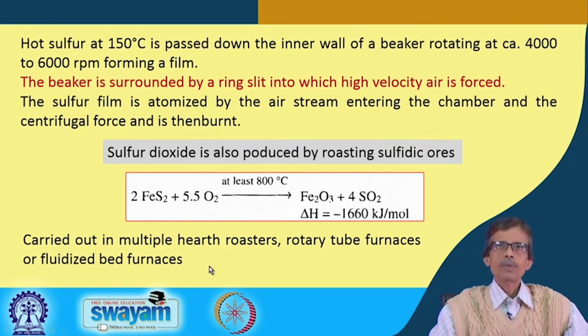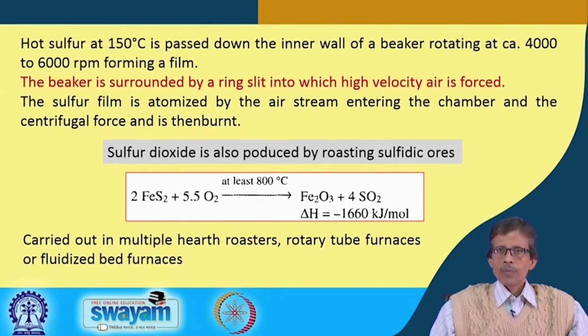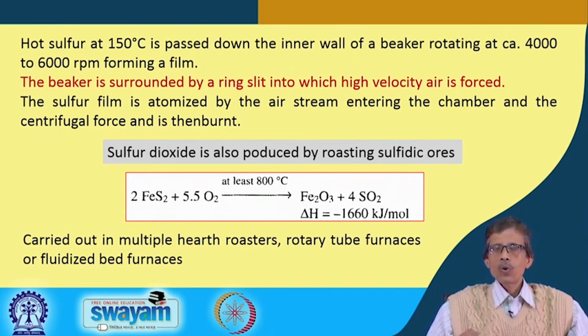Roasting, we all know, is basically a burning process. Ore roasting is a very common procedure for making all these things, and sometimes we get value addition from it. So, if your iron pyrite is not a very useful ore or mineral for the iron or steel making industry, what can we do? We can convert FeS2 to Fe2O3, because we know hematite or magnetite, these oxides like Fe2O3 or Fe3O4, are very useful ores for iron and steel manufacturing.